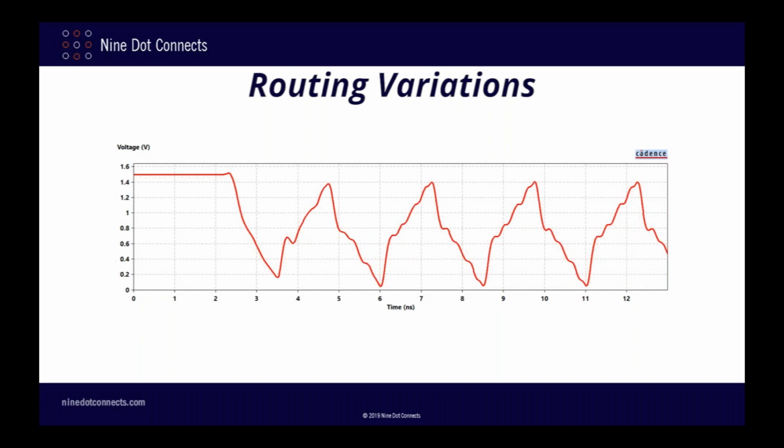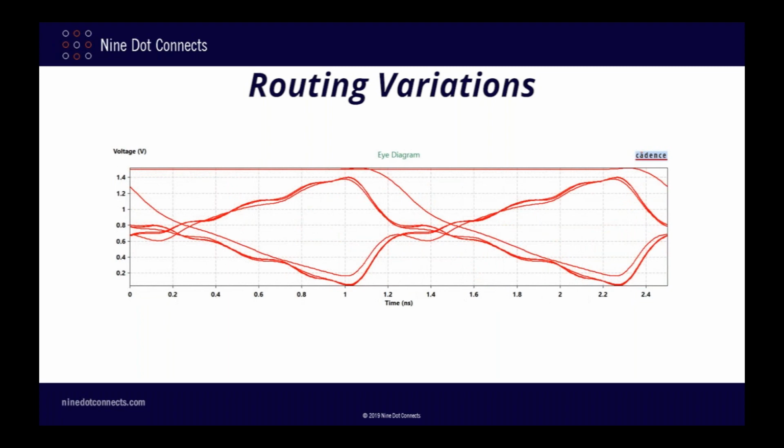So if T-branching were used for the entire ACC group, including the clock, you can see how all of the signals would be clocked at the appropriate time. And here is the eye diagram. Unfortunately, we're seeing some eye closure as a result of the imperfect termination, which is causing some reflections. So here's a demonstration of the downside of T-branching. It's harder to get the termination right.